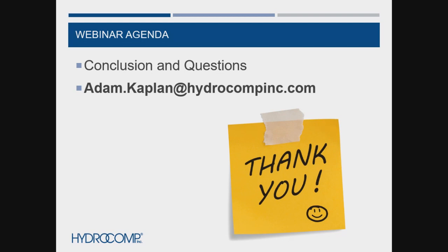But as you get a denser and denser file, that means more points are pulled into PropCAD. And so at some point, you do have to reduce the points in a section to something a little bit more manageable, especially if you want to smooth things out. So my recommendation is I'd probably use something between 50 and 80 megabytes. That's a pretty large reduction from what typical 3D scan files are.